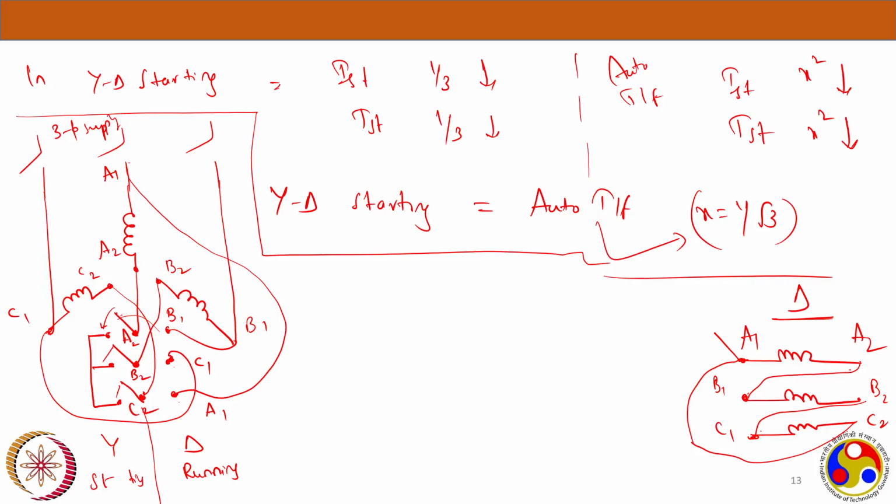Okay. Now the first problem says: consider a 10 kilowatt, three phase, 400 volts, 50 hertz, 4 pole slip ring induction motor. We are given a slip ring induction motor operating under rated conditions, and the maximum torque occurs at 16% slip, and it is double the full load torque. Apart from that, stator impedances, core losses, and mechanical losses were asked to be neglected, and we were asked to estimate the slip at full load.